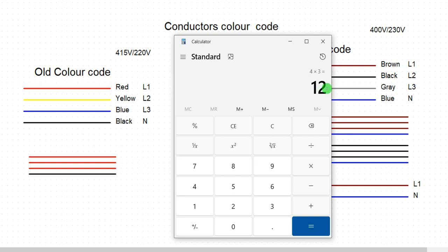Now they are telling us not to exceed 12 volts voltage drop. So in that case, our lighting circuit is going to be 400 minus 12. So make sure you regulate your power, manage your power supply for three phase. On lighting circuit of three phase, make sure it doesn't go below 388. That is your voltage range for lighting circuit.